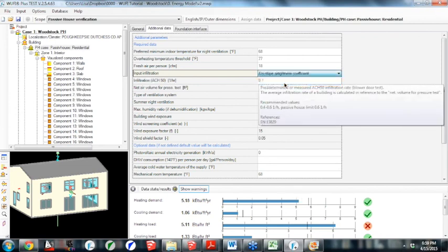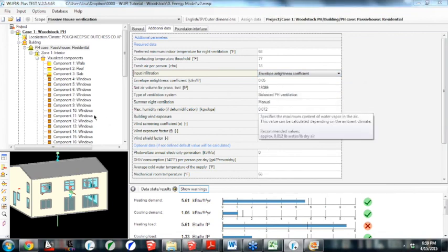Why do you always measure a home run to the water heater? The old assumption with the hot water is that each tap is turned on 3 times a day, so water travels that distance 3 times a day. It figures out the volume of water that fills that individual pipe, and then the energy required to heat that water from the incoming water temperature to the circulation temperature, like 50 to 120. So it's just figuring out a volume of water and the energy associated with heating it, and it's an estimation that the tap is turned on 3 times a day.